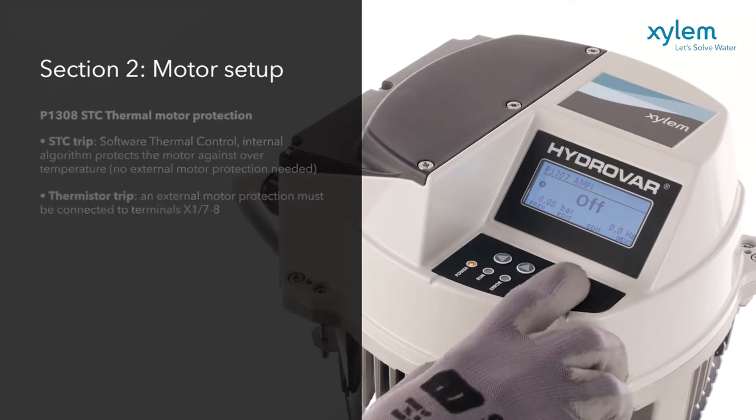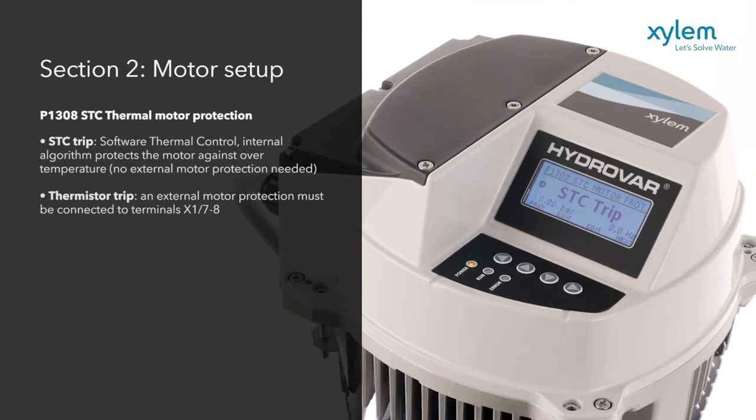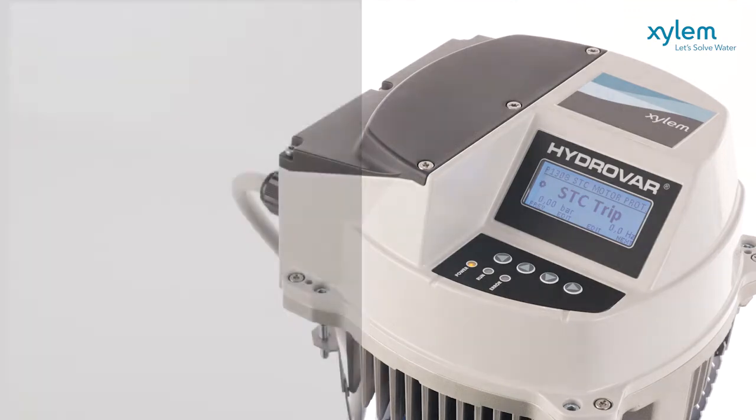It's necessary to select the thermal protection settings for your motor, which will protect the unit from overheating. With the STC, Software Thermal Control, no motor PTCs are required as standard.